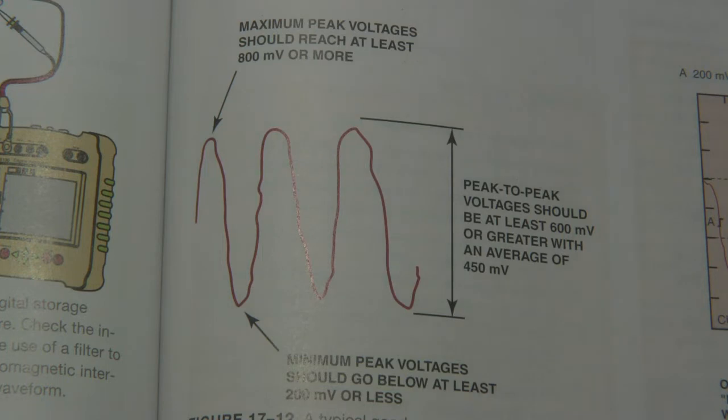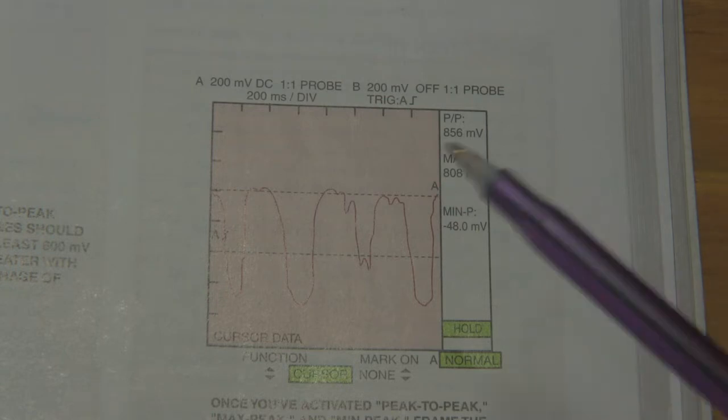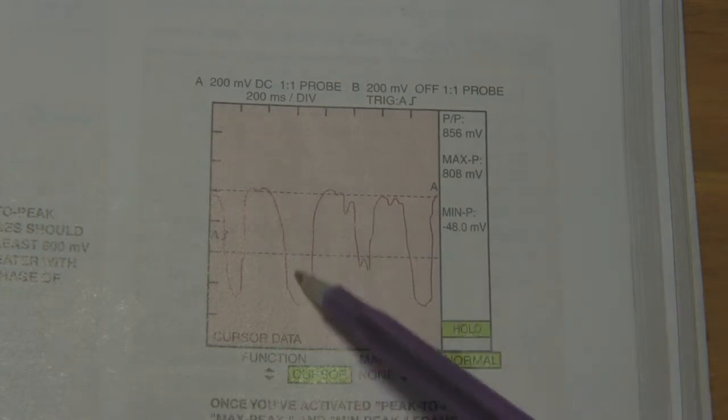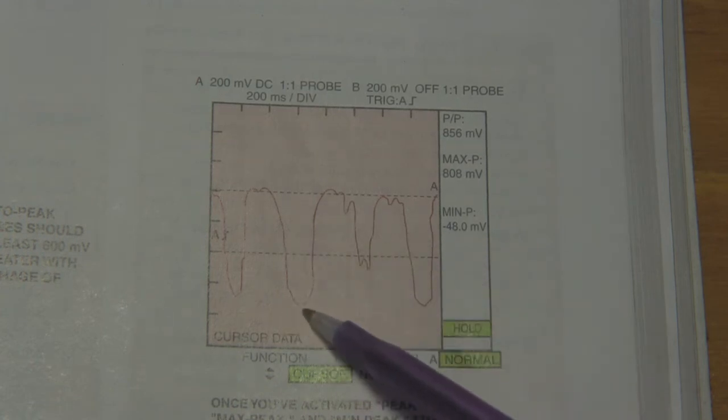So using an oscilloscope to watch this raw data is beneficial when you're trying to find oxygen sensors that are kind of on the edge. When they're close to failing, maybe they intermittently are failing a monitor, but you can make them look pretty decent on a scan tool. You'd want to look for this type of stuff when we're seeing a whole bunch of up and down cycles not quite making it in the full range. So let's take a look over here.